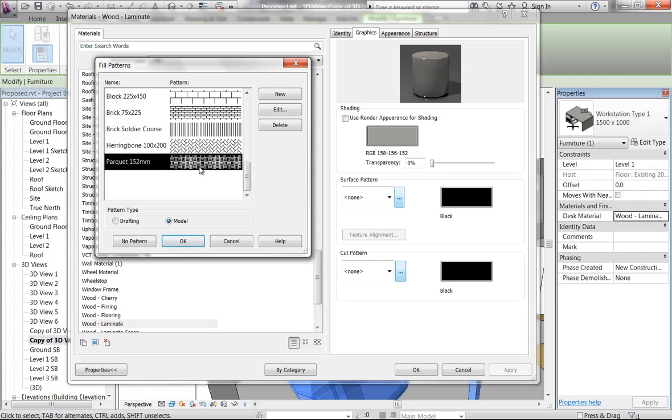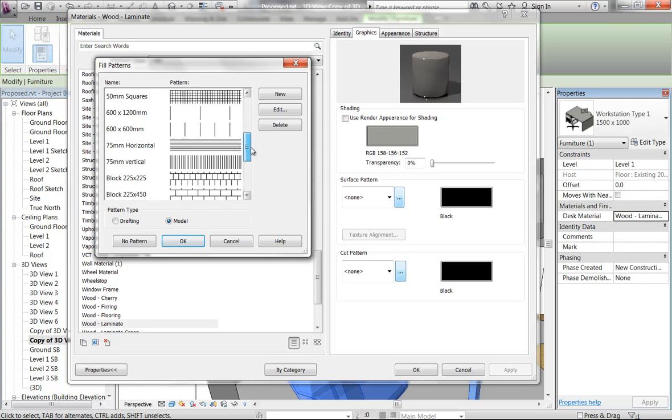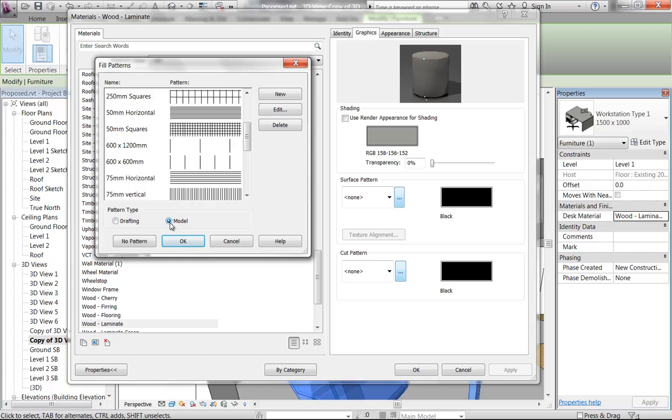And it's called architectural graphics, even though you're doing interior design. Exactly the same style of representation. That's fundamental. More important than being able to do photorealistic renders is the ability to clearly represent materials with these drawings, these patterns that people know, even if they're drawings like this for brick. It might not be the exact size of your brickwork, but they see this brick pattern on your surfaces, they know it's brickwork.